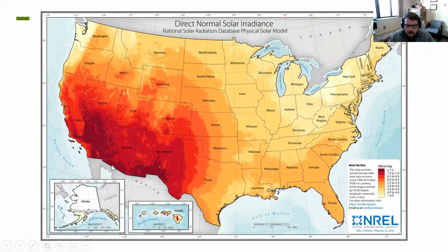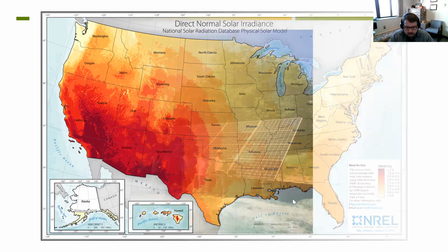As you get into higher solar irradiance parts of the world, they're seeing more hours of sunlight, not only because maybe it's hotter, or they have more hours a day because they're farther south, but also because they have less rain, and so they're seeing fewer cloudy days. Those solar irradiance numbers are based on 15-year averages of actual measured solar irradiance, so the climate and weather are taken into account.